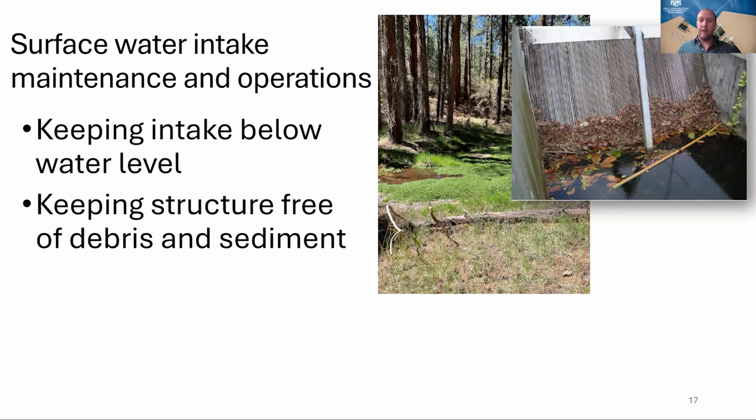So we wanted to make sure we weren't taking in those volatile organic carbons, things like gasoline. So we had a sensor right at the beginning of our intake, and if that sensor detected anything, we'd close the valve for that.